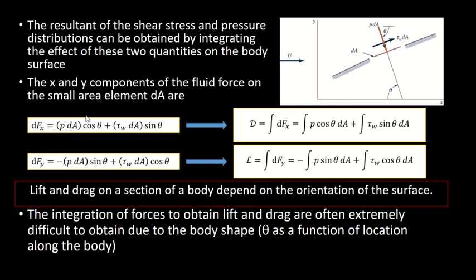Pressure is force over area, so force is pressure multiplied by the change of area, P dA, and then cos theta for Fx, and wall shear stress multiplied by dA sin theta for the shear force.